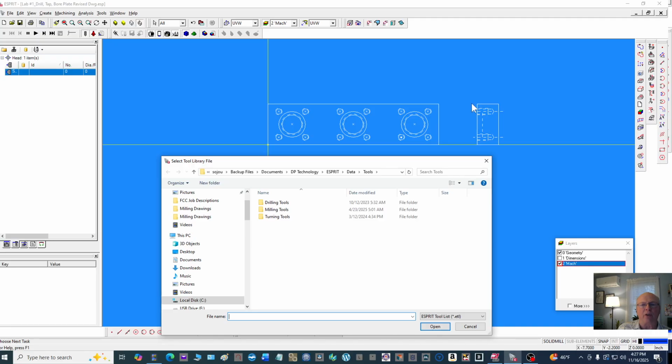We have to add 1/4 of an inch on the material at least just to sit in the vise, and another 32nd on the top to do the face milling operation. So this is going to be a real-to-life type of an operation here now, where we're going to do periphery milling, facing, drilling, tapping, boring, counter boring, and thread milling. All right, just the same way we did with the Mastercam.